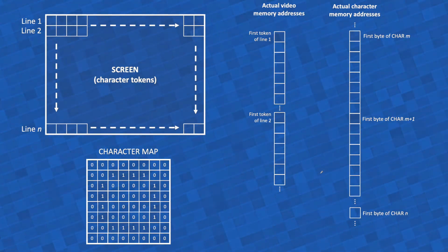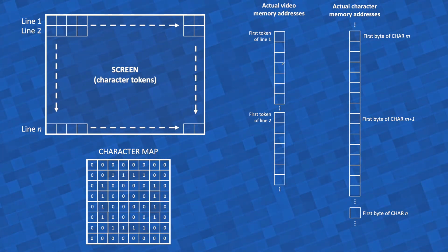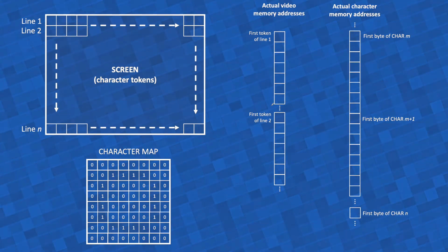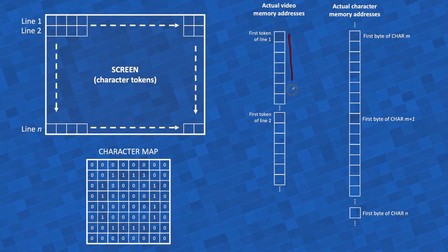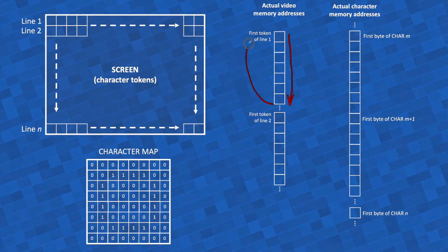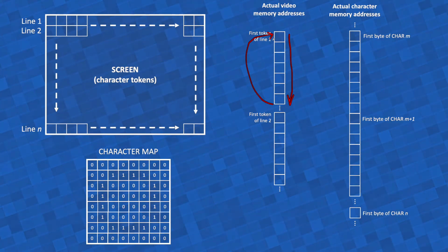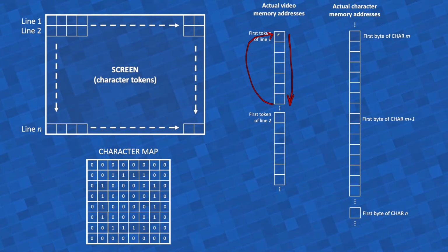So these are not trivial counters. You need a counter to traverse all the addresses of video memory, but you need to give it means to know how many times it has scanned the line. You need to give it means to know where to fall back. I call it the fallback address. That's the first address of the respective token line, and it needs to know that too.